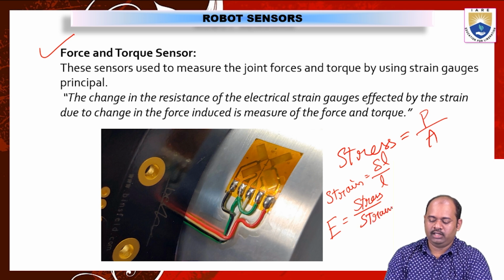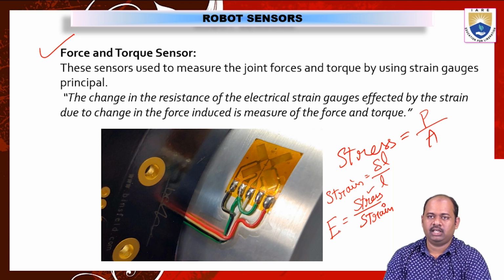So if we want to calculate the stress or strain value out of these three things, we should have any two values. Okay. So if I want to calculate stress, I need the strain value and Young's modulus, that is capital E. So capital E or Young's modulus is the property of the particular metal. It is predefined because the metal with which we are working is fixed at the beginning of the experiment.